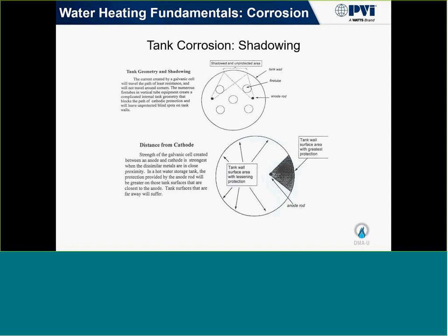And it's also true with distance. So if they only have one or two anode rods in it, the closer you are to that material, the more protection that anode rod is going to give you for that system, which needs to be taken into consideration with design of water heaters and anode rods in general. And with the more fire tubes you throw into a system, the more heat transfer you get. If you're using anode rods, you're also going to have a lot more shadows cast on the side walls of that tank.